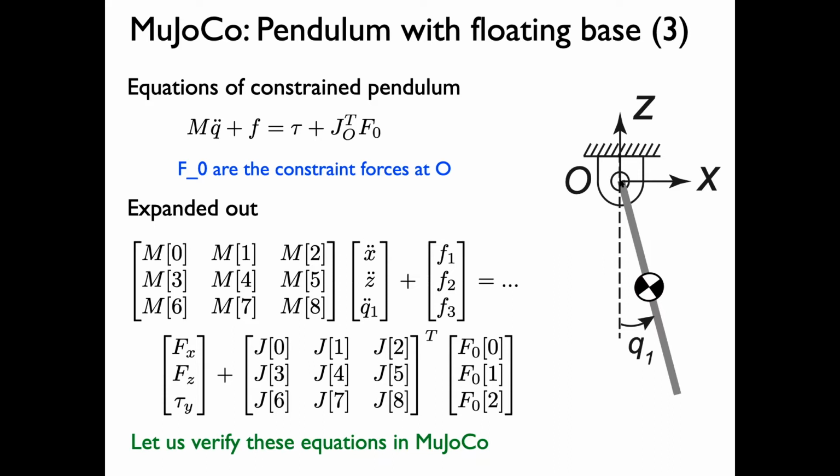So think of something moving at O, you're going to arrest that motion, and you can arrest it by applying a force. And this formula basically gives you exactly what the compensation should be. So when you expand this out, it looks like this. M x double dot, I talked about earlier, all the forces equals Fx, Fy, Fz, tau. These are the external torques. Now there are, as I said, 2 forces for the sliding joints and 1 for the pin joint. And then this Jacobian would be 3x3, and there'll be forces X, Y, and Z.